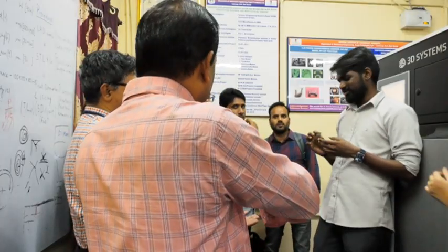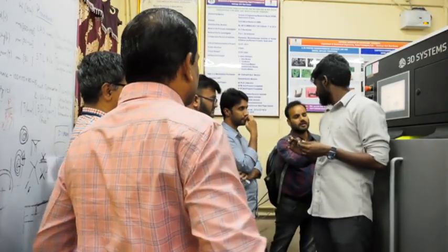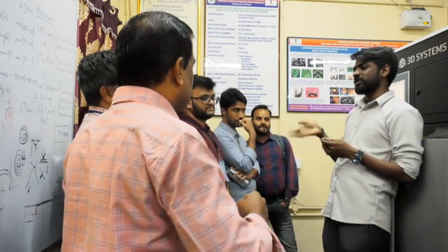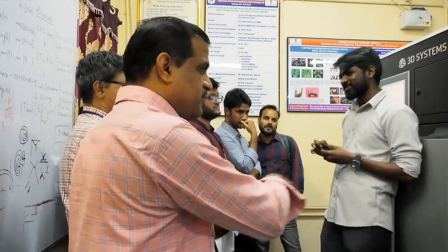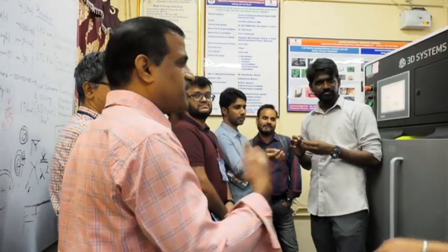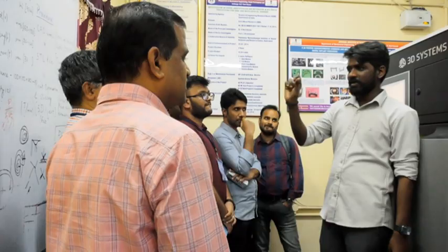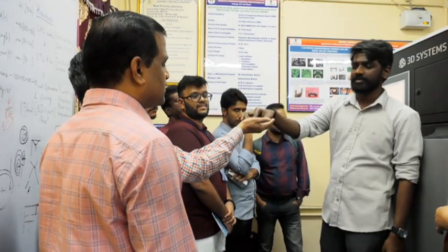It will depend upon the recoater speed only. And again you have to use extra powder also. There will be one ratio, a 1 by 3 ratio. The complete bed has to be spread, so the excess powder is needed. This is the final part, after doing post processing.